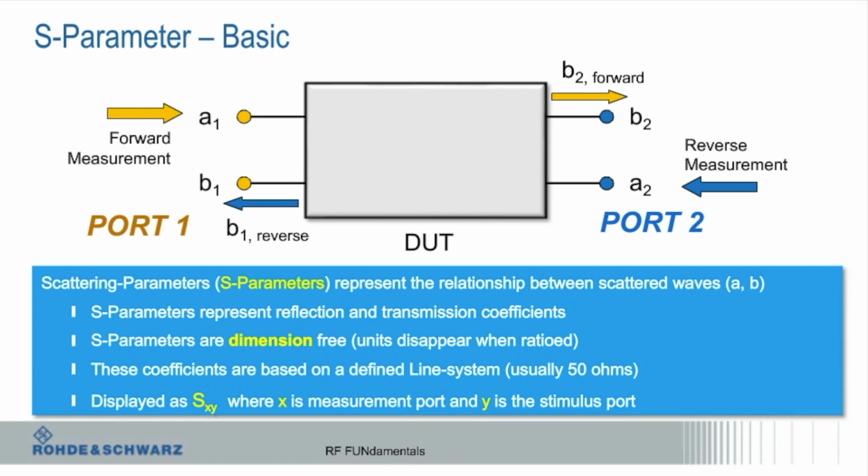So what you want to do is, after you've done your cal, measure something and see whether it looks like it did before, or like the model data that came with the kit. In the case of a verification kit, I have all the S parameters for each component in that kit. So when I'm done with a cal, I'll pull up the S parameter file for that device and put it on the screen. Then I'll put the measurement up, and they should lay right on top of each other, right? So that's really what you should do.